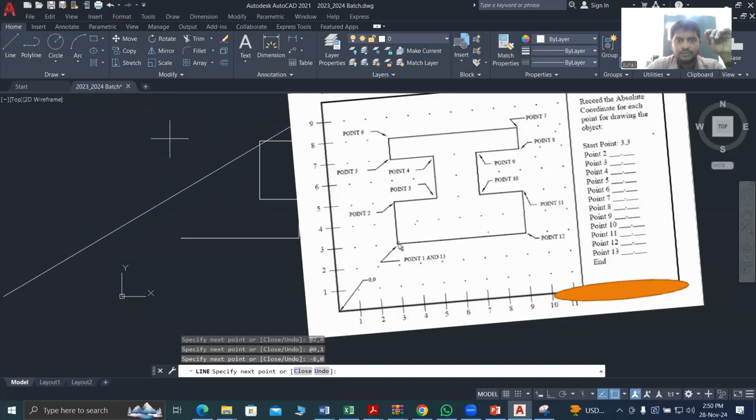No. Sorry. What was the error? I forgot to type the at there. If you forget to write that, it is automatically considered from the origin axis. That is the problem. Okay, then you enter. Then tell me again, shift at minus 6 comma 0.